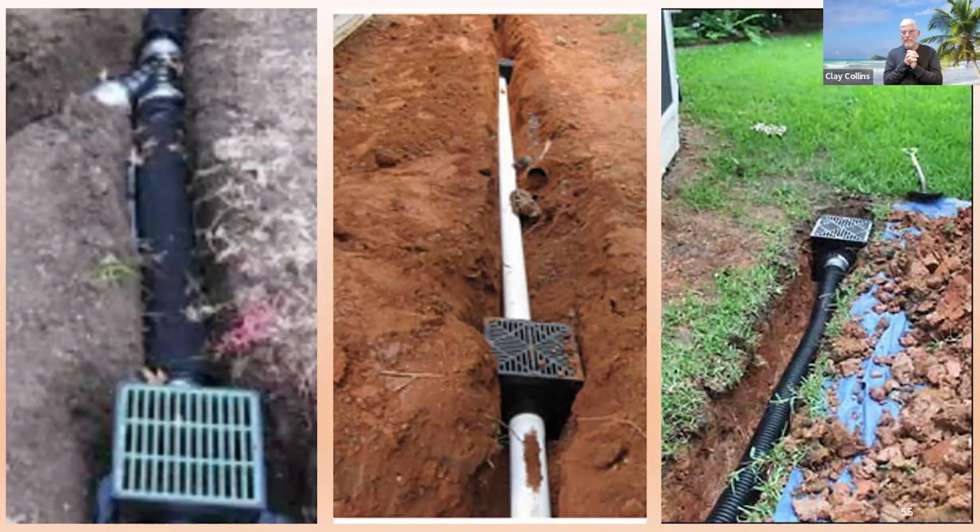The other one doesn't have a leach field. That's solid pipe. That means it's trying to get all of that water that it picks up in the catch basins to whatever discharge point. No leaching at all. That is going to take a little longer to drain, as long as it's raining, as long as it's filling catch basins, because you've got them in series, and it's just going to overwhelm it.